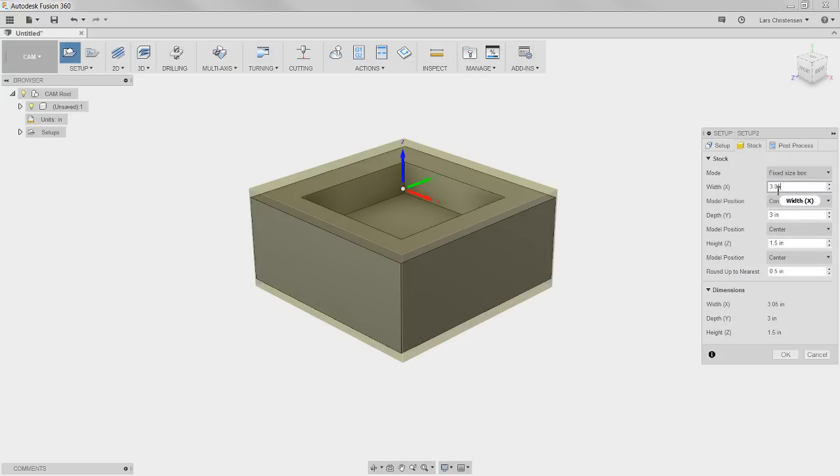Put in whatever that bar is measuring in here, and the saw length might be, you know, an inch and 100 thousandths over, but do the thickness here to exactly what we're planning on programming, not what you're actually measuring it to, because we're touching off on the top, and you will see why I want to do that in a second.